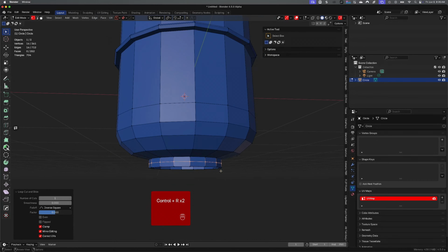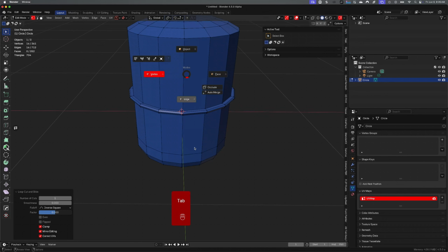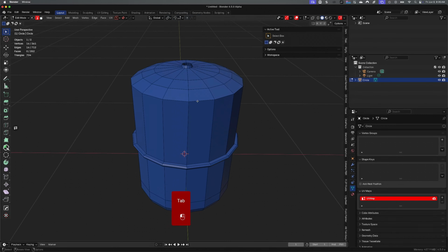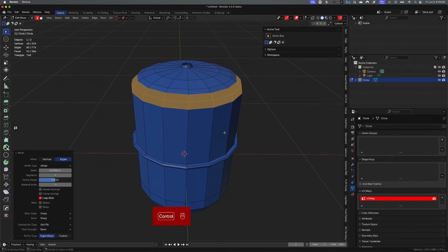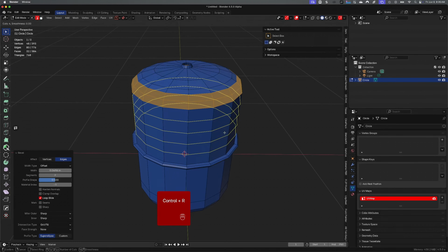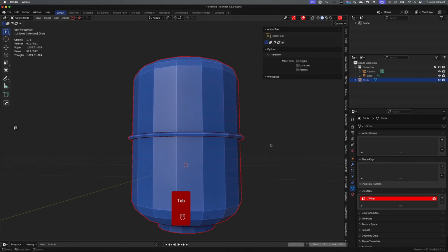Now I'm putting in some support loops here, just kind of to help relax the geometry. You're going to see I'm going to come back in here later and do it to other areas, but right now I want to tighten up some edges with bevels for sub D, because I'm going to run a higher sub D on this, probably a level 3. So it's putting in some support loops for relaxed geometry. I'm adding more geometry in here, but not going crazy, because sub D is going to make it crazy for us. It's going to make it more dense.